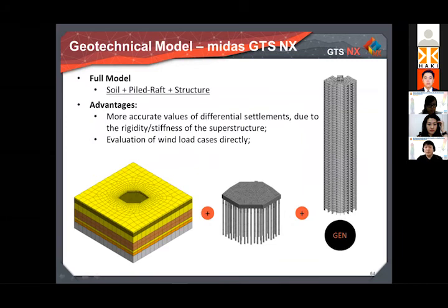Some numerical models of building foundations were made only by applying load or pressure at the base of the columns. It is like retrieving the loads for each column from the structural team and applying them directly to the model. This might neglect the distribution of loads in the superstructure and its stiffness or rigidity, as you wish.